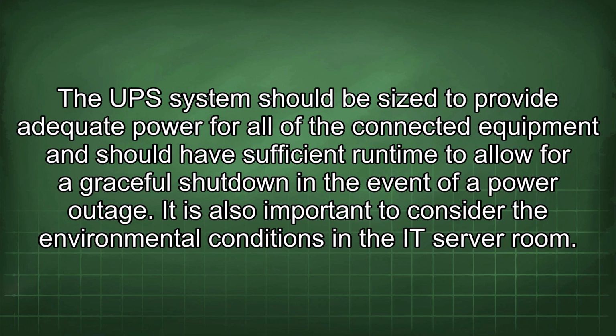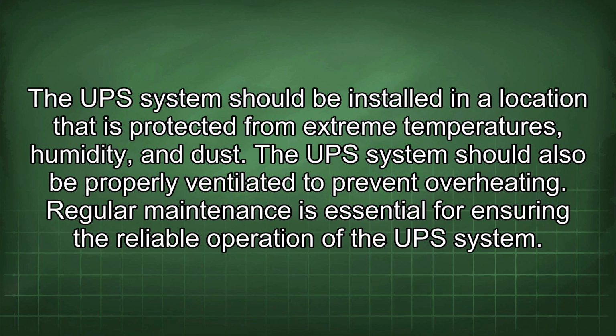It is also important to consider the environmental conditions in the IT server room. The UPS system should be installed in a location that is protected from extreme temperatures, humidity, and dust. The UPS system should also be properly ventilated to prevent overheating.